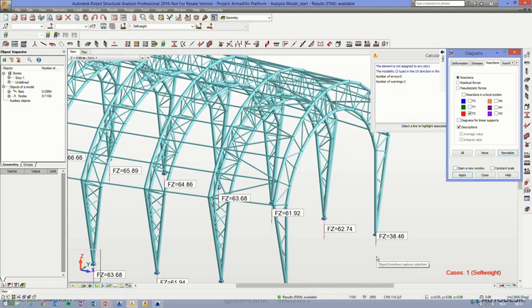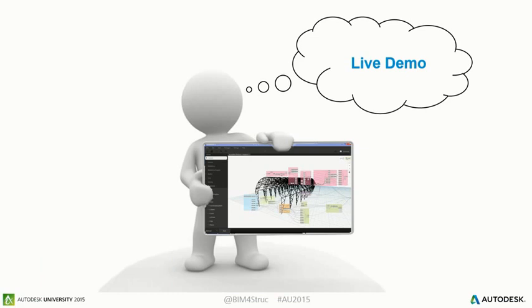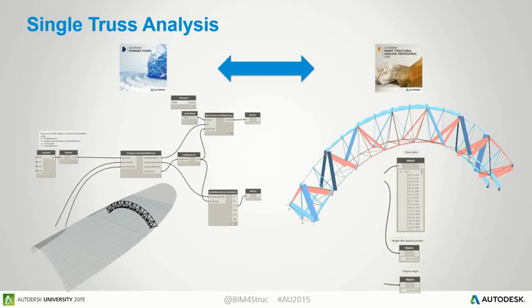Next thing is the boundary conditions. So the analytical nodes, which are these red dots, well, you cannot see them in red at this moment, but these guys here, they need to have a support. Otherwise the structure will fall down, of course, right? So it's a pin support. I want to have releases on it. And so pin fixed releases, pin pinned releases, so that we have a good structure, because otherwise it's completely fixed. We don't want to have a fixed model. It should be flexible, okay?